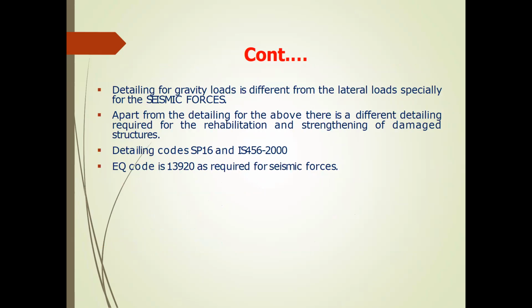Detailing for gravity loads is different from that for lateral loads, especially seismic forces. Apart from the above, a different detailing is required for rehabilitation and strengthening of damaged structures. The detailing codes are SP 16 and IS 456-2000. The code IS 13920 is for seismic forces.